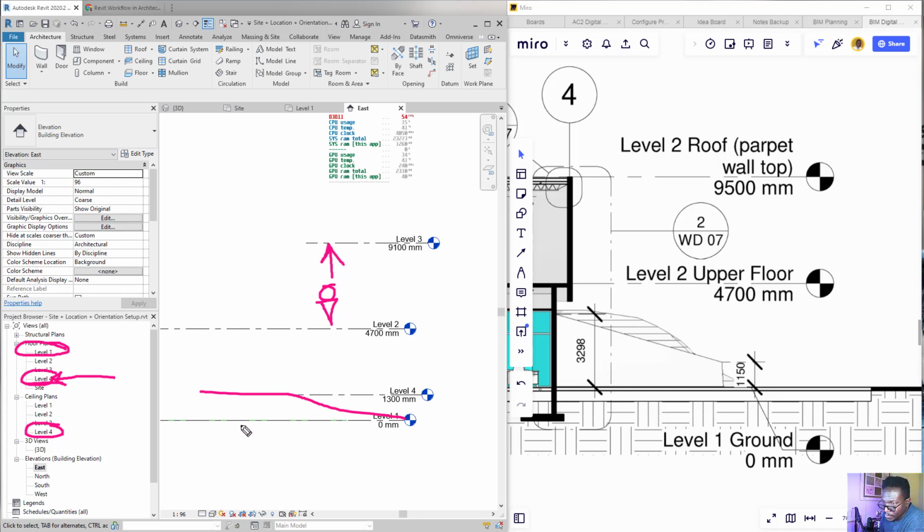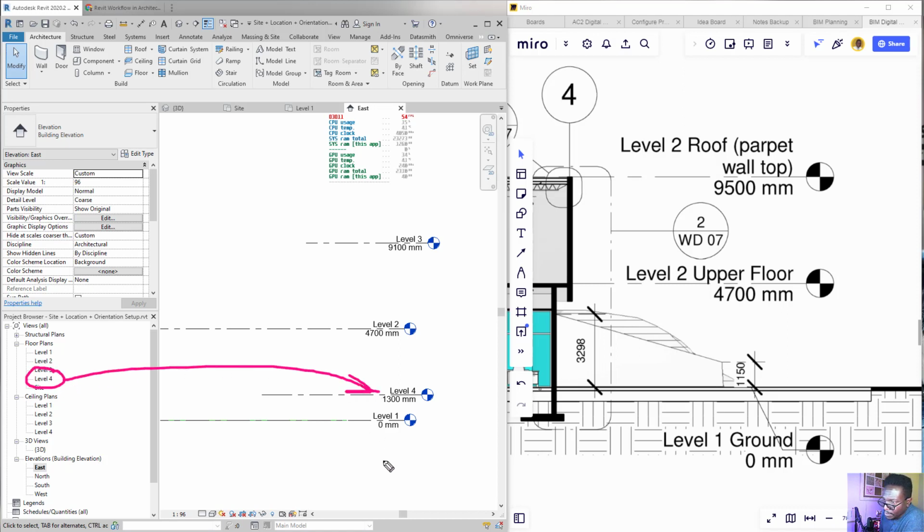Now, of course, there's no reason to generate a ceiling plan under my ground upper slab here. It's pointless. I really just need a ceiling plan here, which would be for my level 2. And maybe a ceiling plan would be for my level 3 if I so choose, right? So in this particular example, a level floor plan, which is here, is a bad thing. So I'm raising this point to say that not every time you want to be creating a corresponding level with an actual level in the drawing.